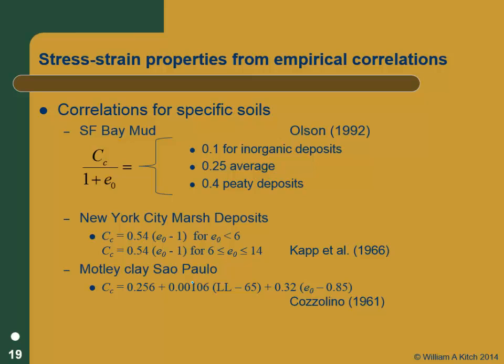And if the settlement is really, really important and really critical for your project, then you better go get samples and do it. If it turns out, hey, I'm computing 6 inches of settlement for this embankment, I really don't care, because by the time I get this constructed, we're not going to care, then fine, don't spend your time getting samples. But if you find out it's important or significant, then maybe you need to go get samples and do your calculations. But it's a good place to start.